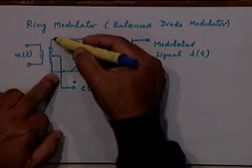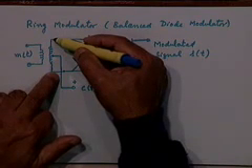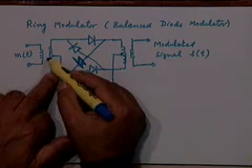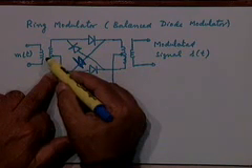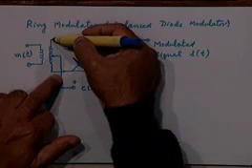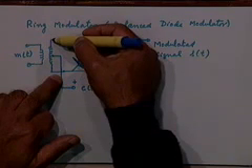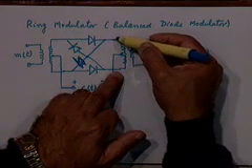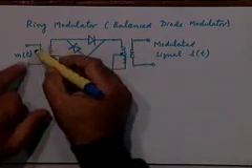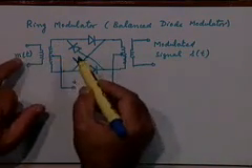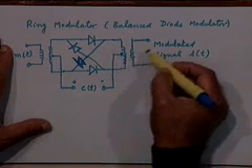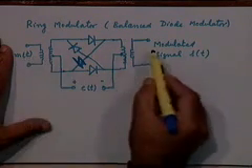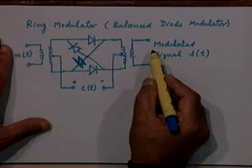The carrier voltage appearing between these two transformer terminals, if the transformer is perfectly balanced, if the center tap exists precisely in the middle of the winding, there will be net zero voltage due to carrier here, and similarly net zero voltage due to the carrier here across these two terminals. So basically this voltage M of t, assuming this is unity gain or whatever, will appear across this output. So you will get M of t multiplied with 1 at the output in this case.